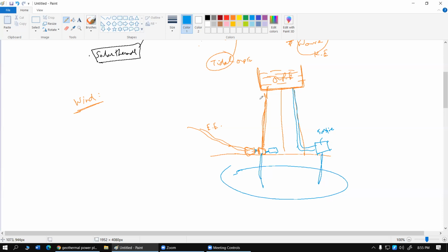So the idea is that using this mechanism, we can store some energy. And when the water flows out through this pipe, it is going to flow through the turbine. The turbine will be connected with some generator, or if smartly designed, a single turbine can be used where it will be alternately connected to the motor and the generator, one after another, not simultaneously, for different durations of time. So this is one way to reserve the electrical energy, one practical way.